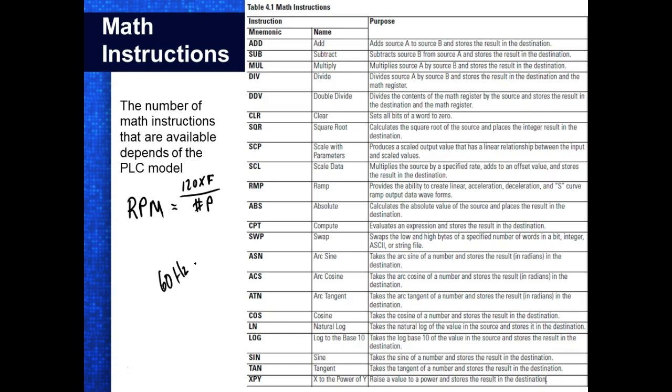You also have to control the voltage too. They call them variable frequency drives, which is what you use to electronically control it. These come with a little push button panel that you can program all kinds of stuff on, and they're not hard to program. You just look at the nameplate on the motor and enter the information off it. Then you can program how fast you want it to accelerate and decelerate. Once you've got it running, there's a little push button on the front. You can press it to increase or decrease the speed. It's really cool. If I wanted to control it from the outside, we send a signal, and depending on the ramp, that's the speed the variable speed drive will control it.